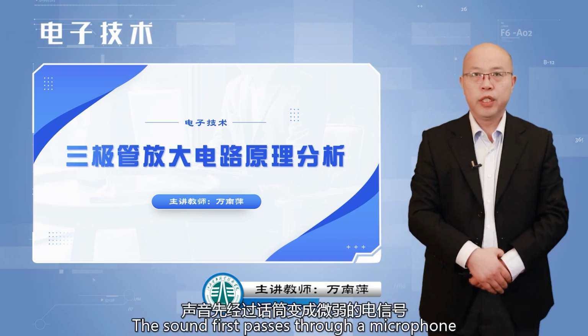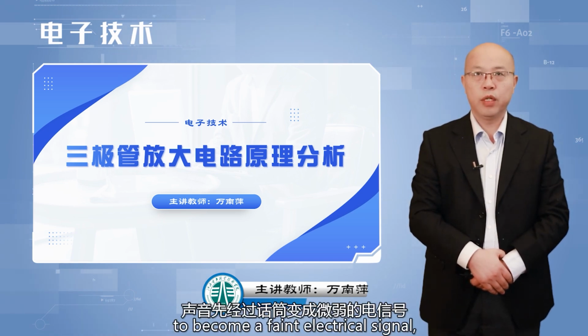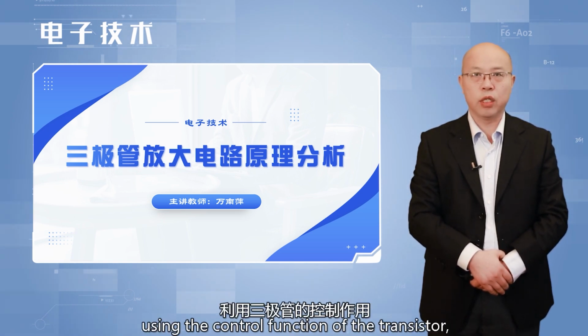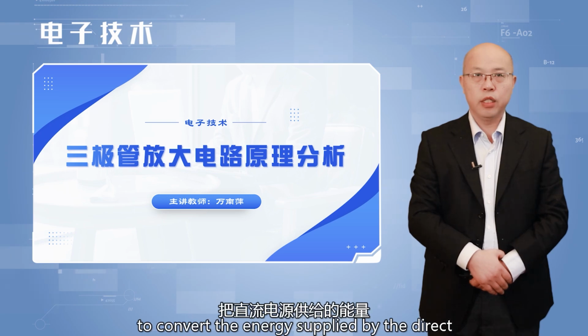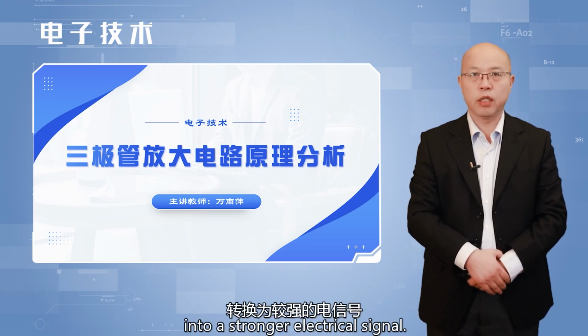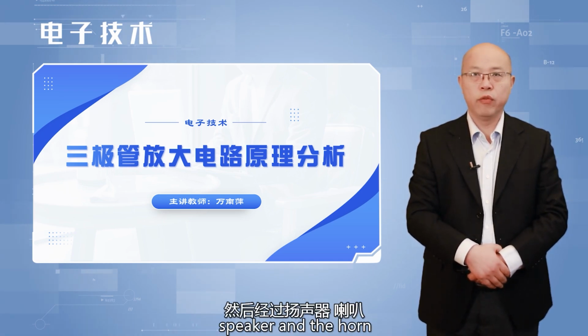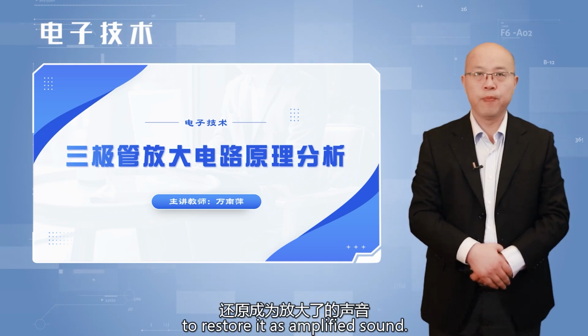The sound first passes through a microphone to become a faint electrical signal, then through the amplifier, using the control function of the transistor to convert the energy supplied by the direct current power source into a stronger electrical signal, and it passes through the speaker and the horn to restore it as amplified sound.